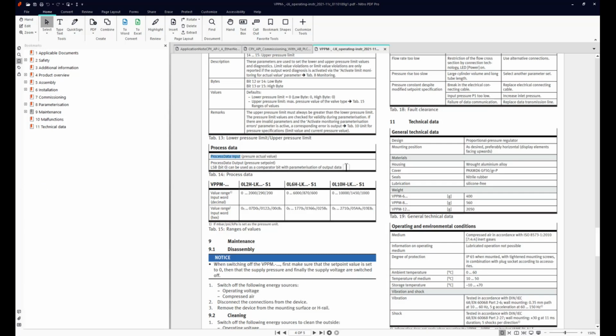And it's also a necessity to understand that an IO-Link Master uses a Motorola CPU, which is big endian, which has the high order byte at the start address. And because the 4IOL is transferring the data to the CPX-AP-I-EP, which is connected to the Allen Bradley, the Allen Bradley uses an Intel Atom CPU, which is little endian. So in order to look at the data properly in the PLC, we need to do a byte swap with